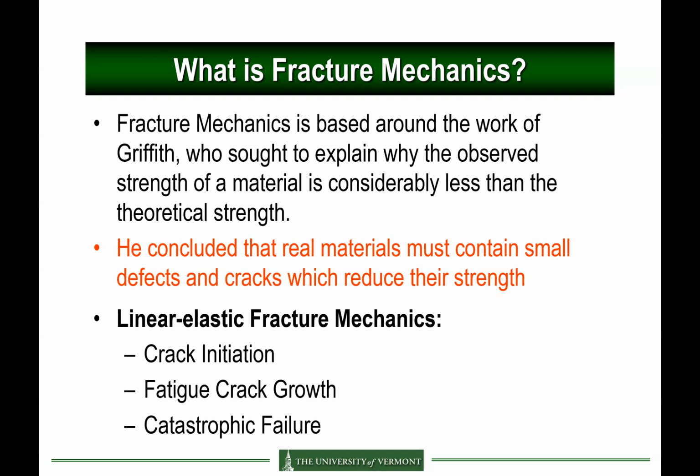And then the last stage represents the catastrophic failure of the material simply in one loading cycle. In this laboratory, we are more concerned about the third aspect that relates to the catastrophic failure. However, you'll see that stages 1 and 2, which relate to fatigue, are necessary in the protocol to measure the fracture toughness of the material.